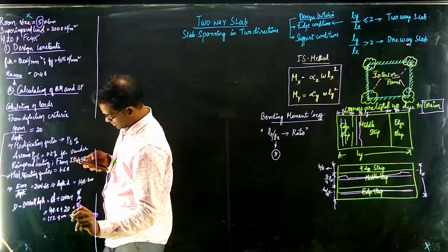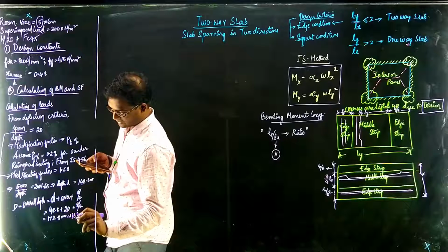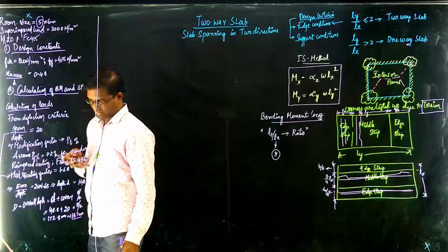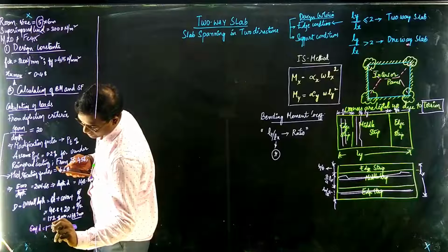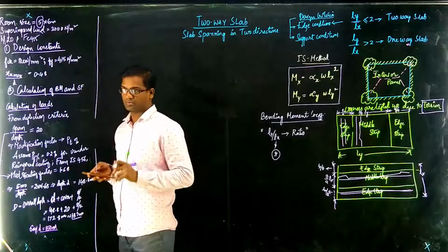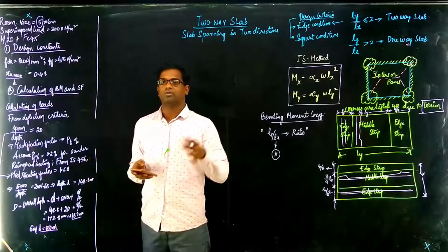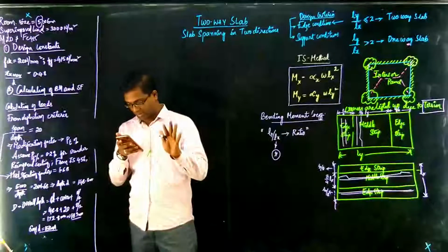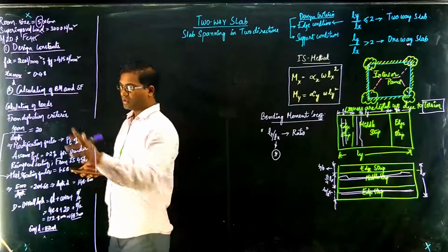So hence say this as 180 mm and small d as 150 mm. For our calculation purposes only, we have to take this. Then when you have got overall depth and d, all that we need to do is calculate the moments and check whether the 150 mm is good enough or not. So before doing that, we need to calculate the loads.